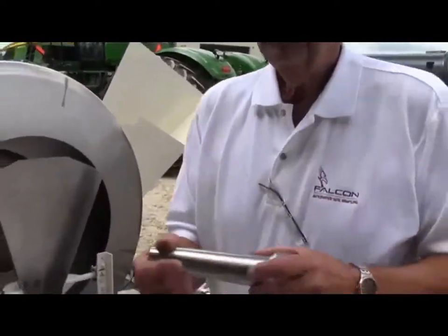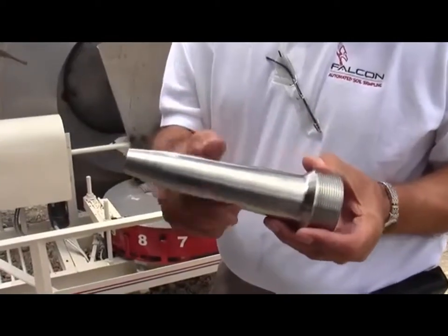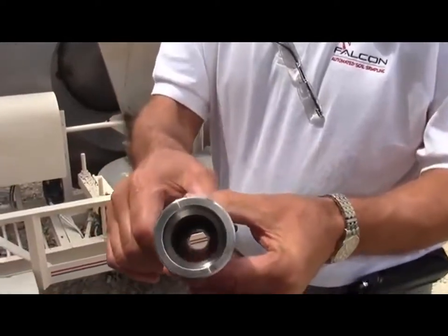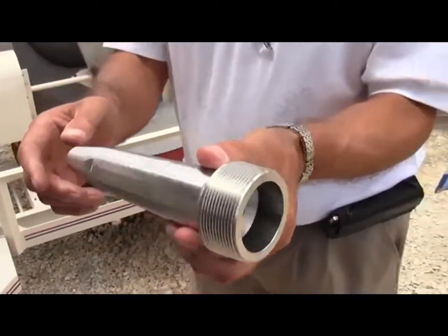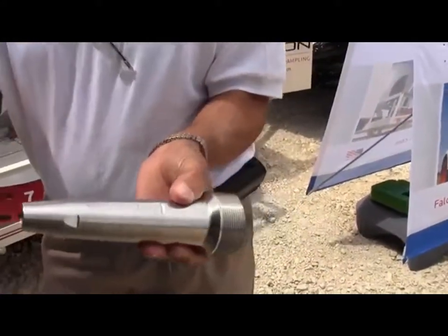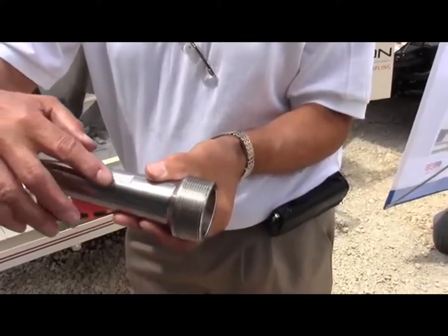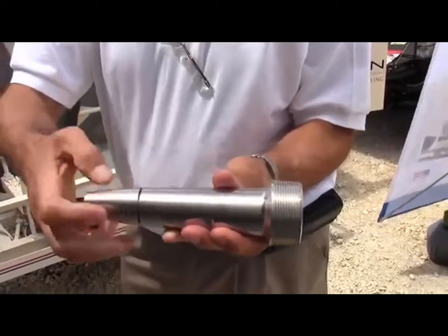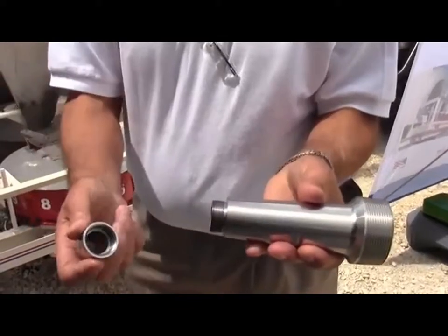And the other thing that allows it to operate is the probe. The probe is chamfered on the outside and chamfered on the inside, if you can see. So the smallest point of the probe is the point of entry. As it goes around, the dirt and soil is continuously released, allowing it to fall. In addition, this probe is two-piece, has a replaceable tip.